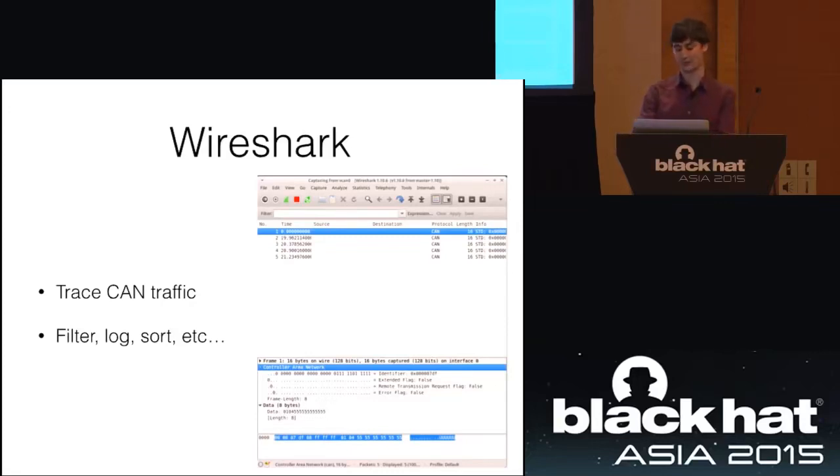And I've been using this actually for work a lot because you can write custom CAN scripts for interfacing with whatever system and then just fire up Wireshark in the corner and it will just tell you what's going on on the bus at all times, which is quite handy.